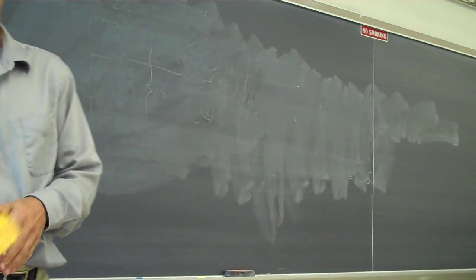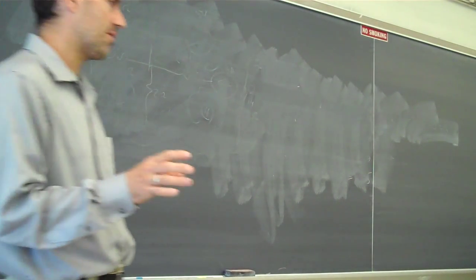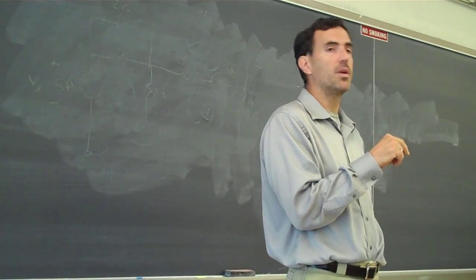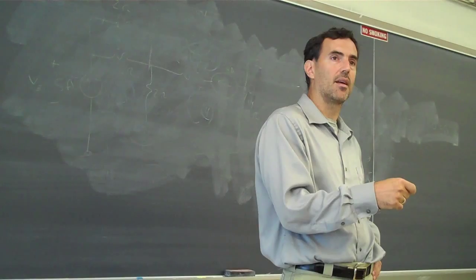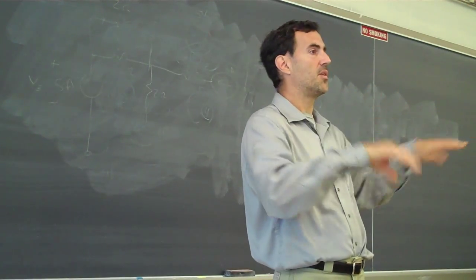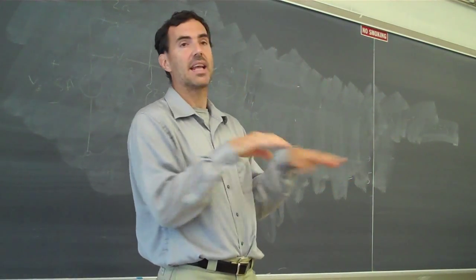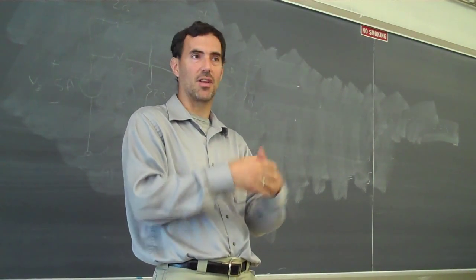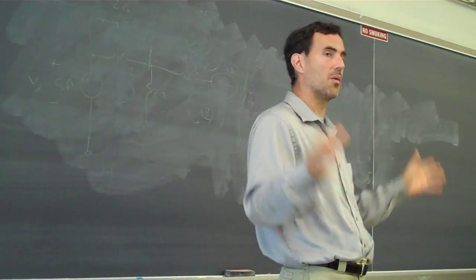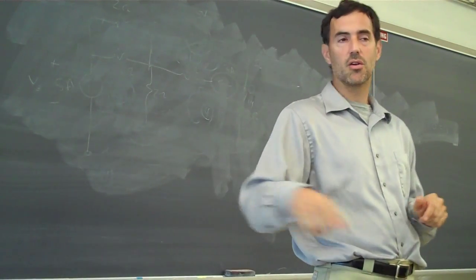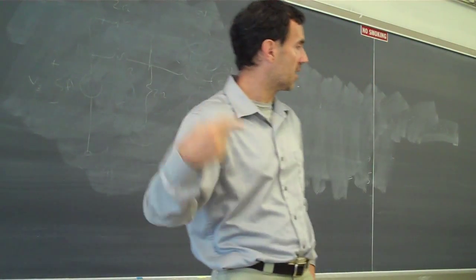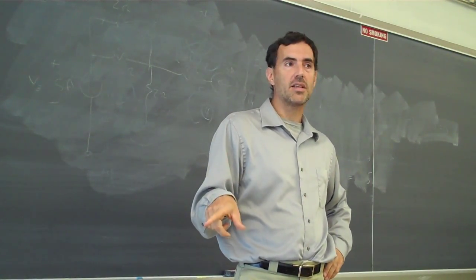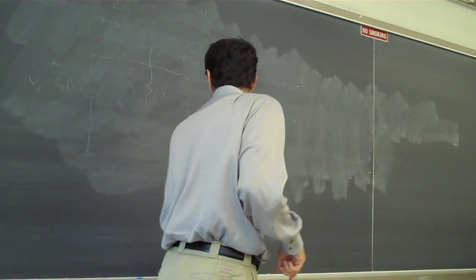The RMS. So on AC, it reads kind of the average. But we want to get a meaningful average. We don't want to just get 0. So what we do is we first square everything, and that makes all the values positive. So we square it, take an average, and then take a square root. This is kind of a clever way of getting an average of stuff that otherwise would have been 0. So that meter reads the RMS value, the root of the mean of the square. So we're getting an RMS value of 116.